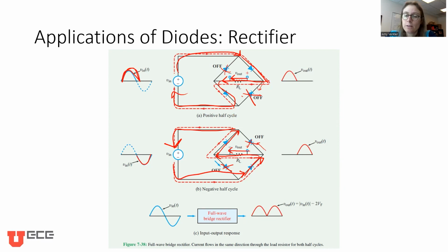So that means that we actually got a positive voltage out each time in this circuit. So even though we input down here below, we can see we input a positive and then a negative voltage, we got out positive voltage and then positive voltage. So that is called a rectifier. And that is just two examples of circuits you can build with diodes.